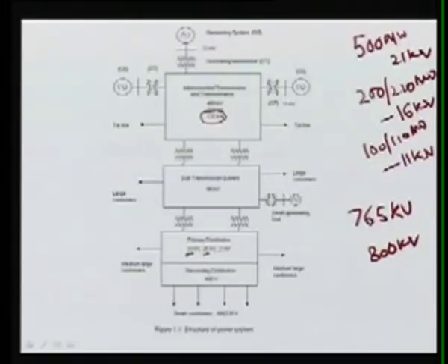Some of our customers, like your railway, take power at 132 kV. Some big companies like the Fertilizer Corporation of India, FCI, also take power at 132 kV. So we have the intertie lines, and we also supply the very large and the large customers. Those require power at very high voltage as well as high power. Also we go for medium voltages, and the medium customers take the power at 33 kV or 25 kV, like your railway. For traction purposes, they normally use 25 kV and the 11 kV transformer.